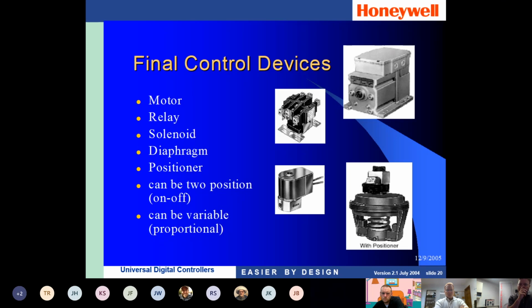So make sure that if you have thermocouples that you're changing those out periodically. You do have to change those out every once in a while based on how many times you go above a certain temperature. The resistance of those thermocouples will start breaking down over a period of time, and then it will get to a point where it'll actually fail open, preventing you from being able to do process control. So make sure that your thermocouples are changed periodically.